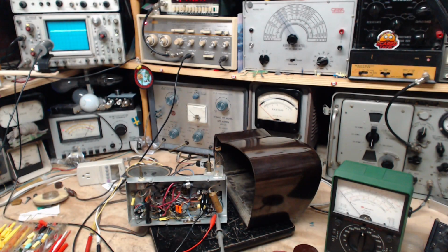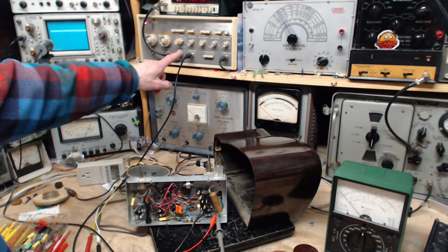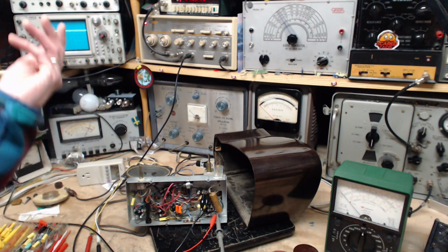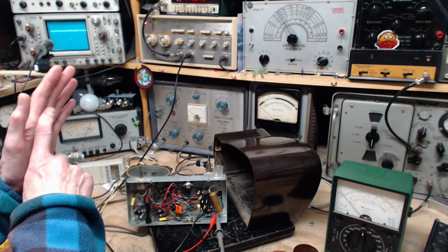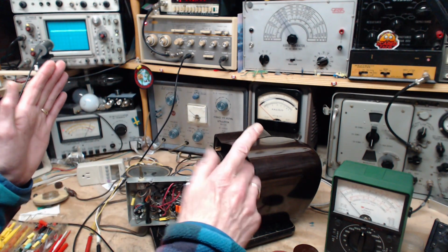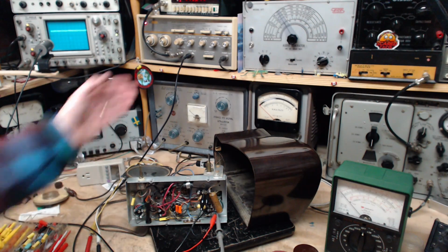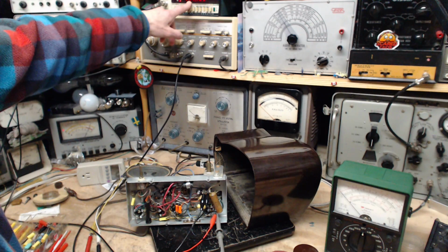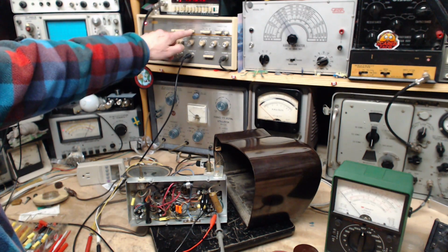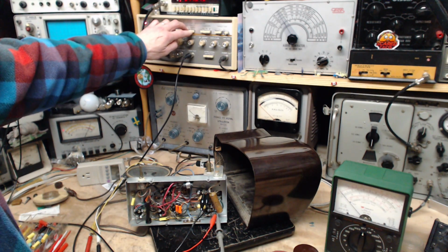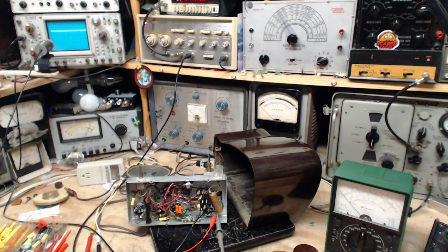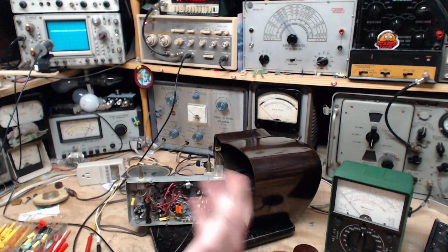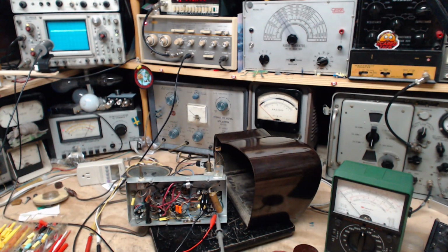Okay, here's my first attempt at finding something out. I have a sweep generator operating here. This is producing a radio signal. It's sweeping from a lower frequency to a higher frequency and doing it at a nice steady rate. I'm starting way low at 144 kilohertz, and it's going all the way up to about 700 kilohertz. In the middle of that range, roughly in the middle, is 455 kilohertz.